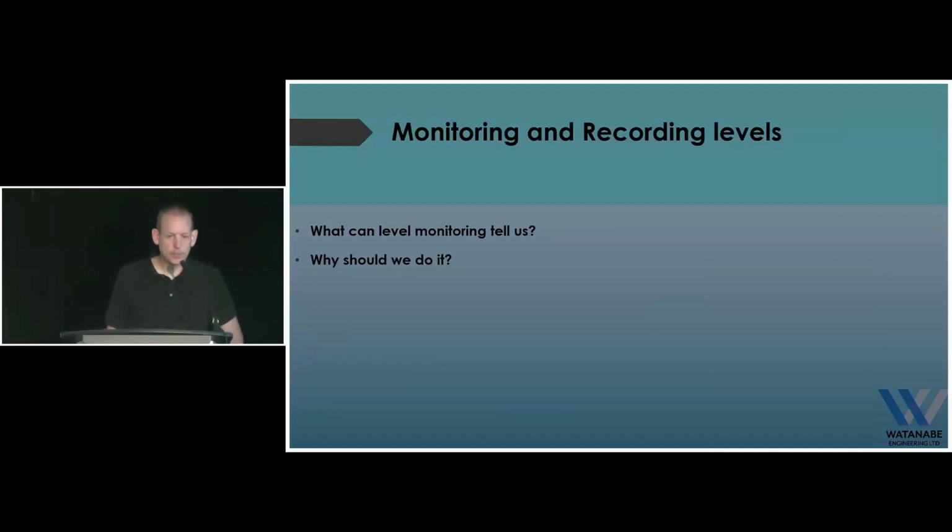So monitoring. We talked about float-based versus analogs here, and a big reason that I like having the analog is that I like to see what's going on. I get so many people that call us up and say, hey, I've got a problem with my sewer station, and we take a look at it and it's float-based control, and I'm like, well, I've got nothing to go on. I've got to come and do some diagnostics on site, try and figure out what's actually happening. Whereas if I had some trend data, to see what's going on with the level, I can probably tell you what's happening inside your wet well.